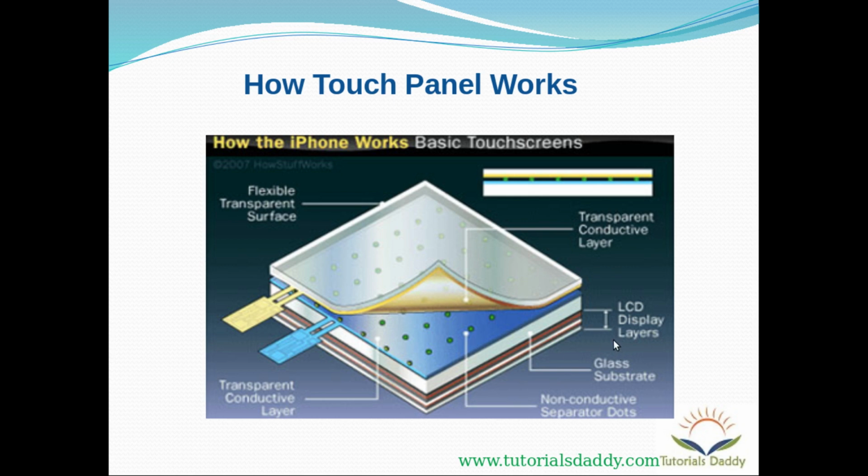This is basically the LCD display layer. Among these many layers you have the LCD display layer, which is your display layer. Then you have a glass layer, then non-conductive separator dots, then transparent conductive layers, and then a flexible transparent surface. So your display is made up of different layers: some non-conductive layers, some conductive layers, and a transparent layer.